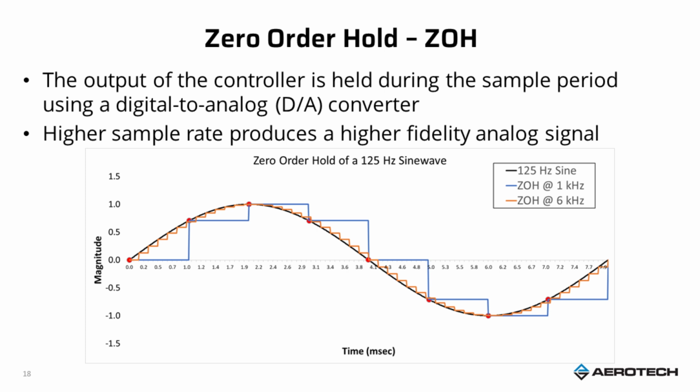Well, it's a linear system, so just picture that every millisecond I'm putting a small step in. I'm going to have a step response to that, and I have some oscillation, I have a little bit of overshoot. And so this introduces some movement in the system that might be undesired or not as desirable. So minimizing that sample time can help us minimize the amount of time the zero order hold puts the step response in and will give us a better response to the system.